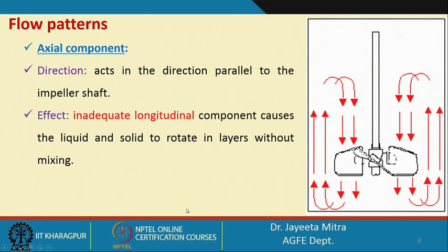So, if an inadequate longitudinal component takes place, that will cause the liquid and solid to rotate in layers without mixing. So, this axial component of the mixing should be proper, particularly when it is a case of a solid and liquid mixture.